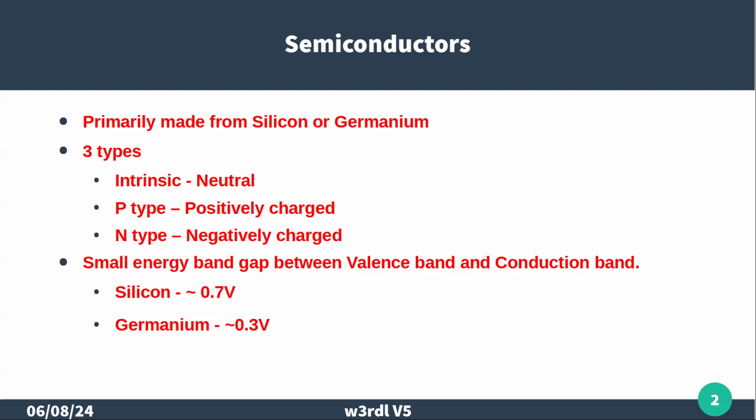Because it's a semiconductor and you have those charges, if you remember, we talked about the band gap for semiconductors, where there's a separation. It takes a certain amount of energy or voltage to have charge cross that gap. In the case of silicon, it's approximately 0.7 volts, and in the case of germanium, it's 0.3 volts. Those are important numbers because they're on the test. Or maybe.